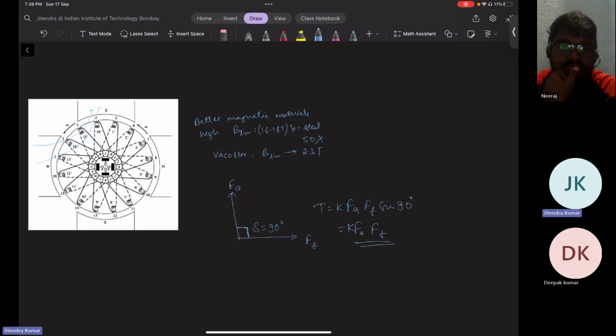As far as the DC machine is concerned, here we have a dedicated separate field winding that is provided on the stator, and the armature winding is carried on the rotor, which is responsible for creating your active output power or torque. So the field winding portion is responsible for generating the rated flux. That's why you tweak the field voltage supply to control the flux in the machine, and you tweak the armature supply to control the output power.